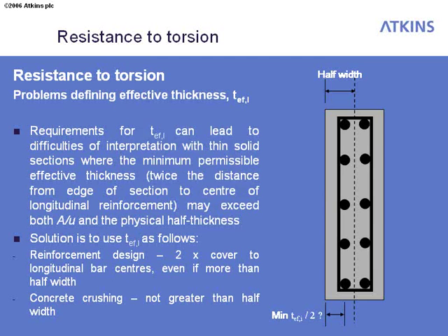Basically what's happening here is this hollow wall beam theory is breaking down, because the wall thickness, by definition in that analogy, is supposed to be a small percentage of the section dimensions, whereas here it's becoming bigger than the section dimensions. So to fudge it, to get it right, we have to go with twice the cover, even though it creates a physical nonsense.